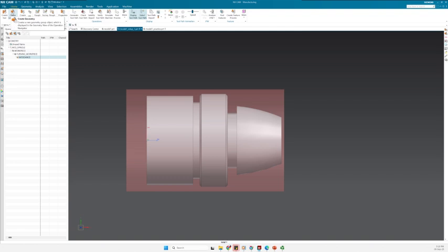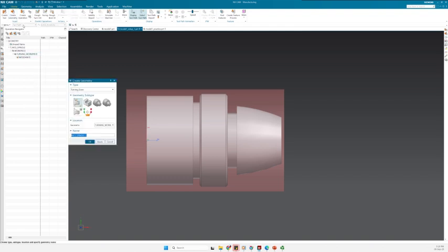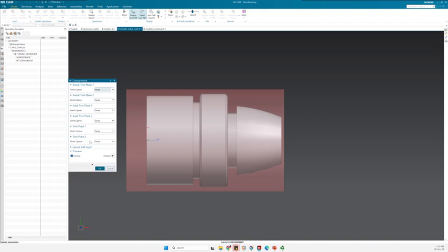So I will create a geometry here. Containment, yes. I will create the containment. So this is defining the axis on an axial plane so that there would be no overpass of the tool along the axis of the machine, since it would be reserved for the spindle.